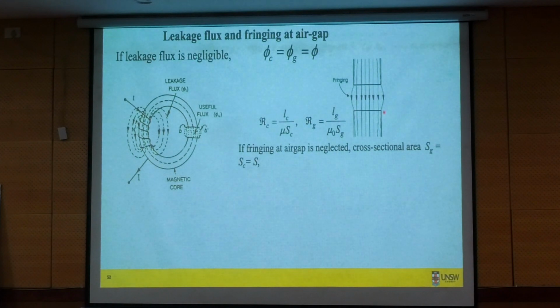So in the equivalent magnetic circuit method, you ignore fringing, you ignore leakage, you even ignore saturation. That's why this method may not give you accurate flux information, and it almost always overestimates it.